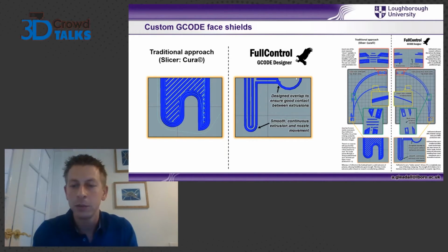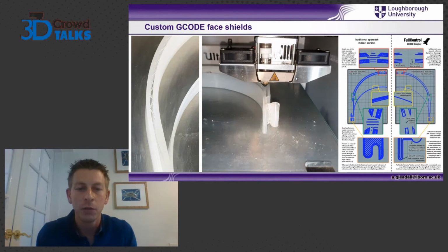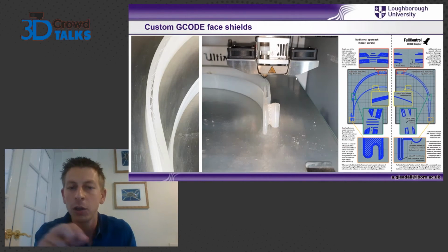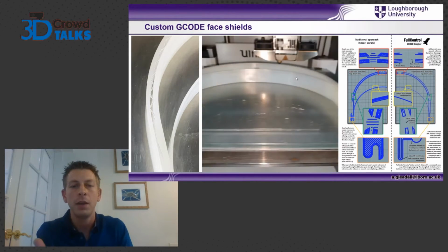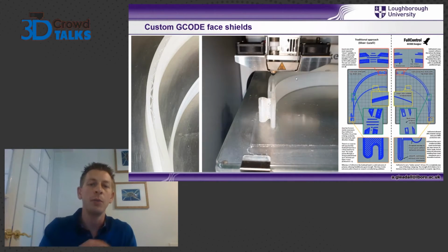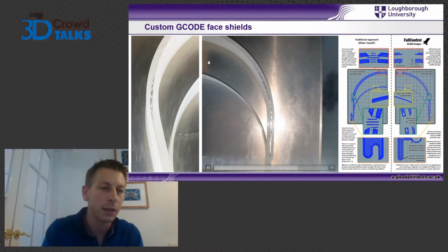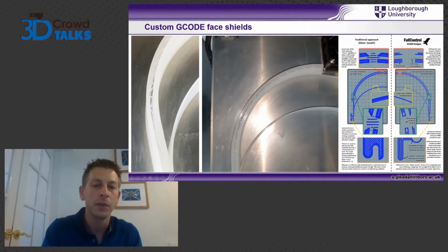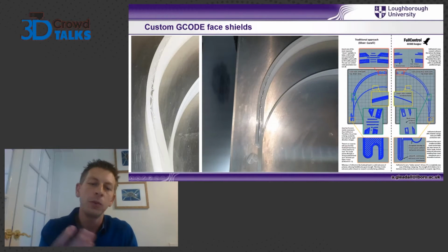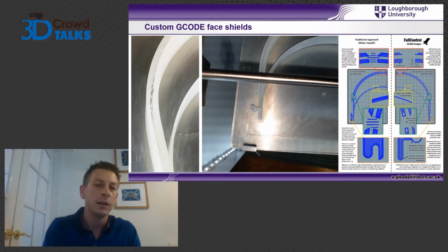And then another aspect that was really cool was printing when we had to have some bridging, was just printing these sinusoidal, what do you call it, just a bridge, so that then on the next layer we could print solid material on top. So you can see on the left-hand side, that's what the sinusoid support structure looks like. And it was fully designed, you know, how much it overlapped with the existing bit and that sort of thing, so that we could get this really nice, consistent bridging with no messy bits or anything.